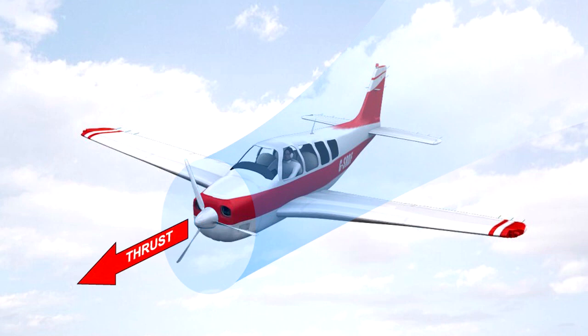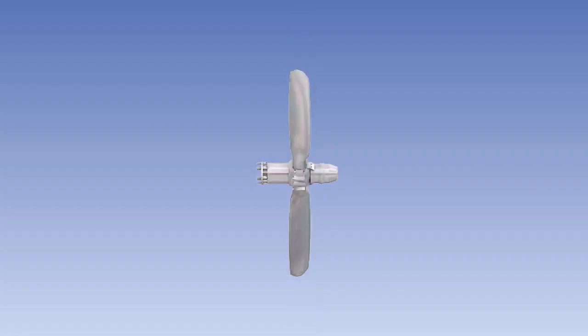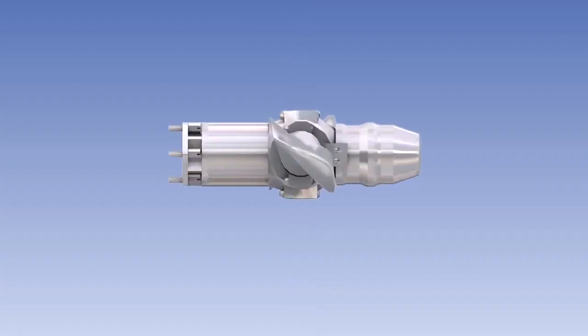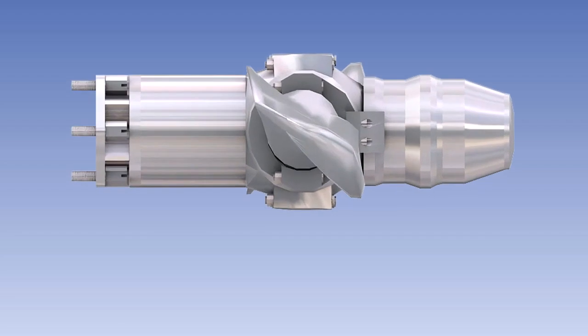The propeller engine generates its thrust in a similar way to the jet engine. A mass of air is still accelerated rearwards, but the propeller is acting much like a wing in that it produces lift, only this time in a forward direction. You will recall that if a mass of air were to pass over an aerofoil, then lift will be produced. In order to pass air over the propeller so it can generate lift, it must be turned through the air by the engine. Shown here is a propeller in cross-section.